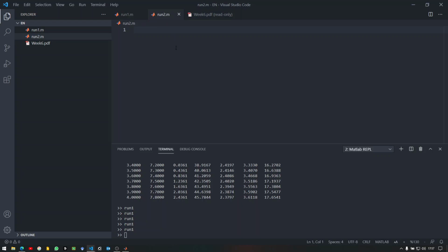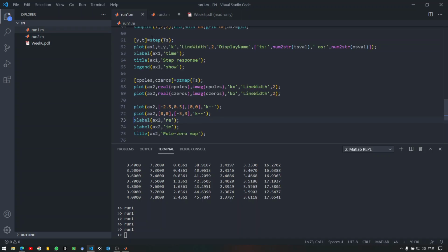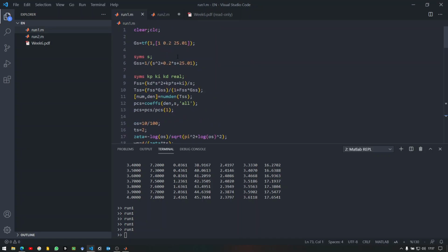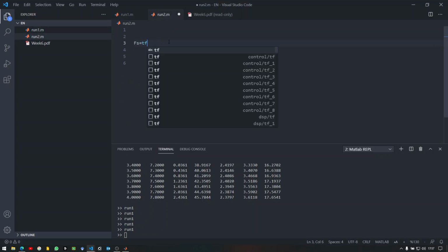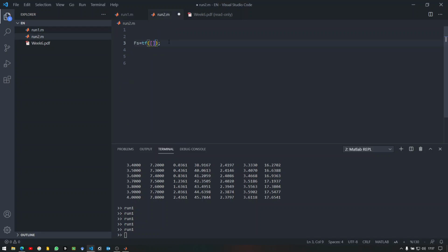Now, therefore, I can just go ahead and look at my system transfer function that I've defined here. This would be my zero polynomial here. I know that if I'm using a PID controller, I am trying to choose two zeros, and I'm trying to place a pole at the origin, and I'm at that point updating the loop structure so that I have a different root locus than if I would have had a P-type controller.